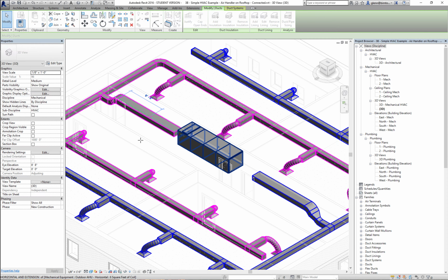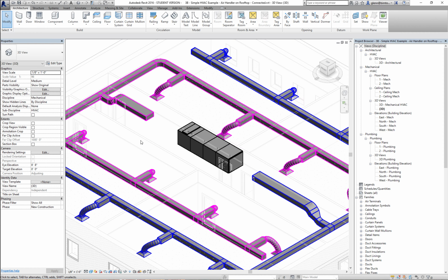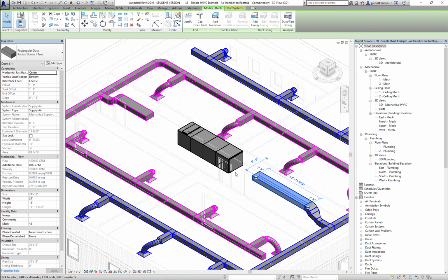And I'm trying to connect these things. Space is definitely one of those things you have to play with. If you're going to have troubles anywhere, the problem you're typically going to have is, do I have enough room to make all the necessary elbows to get this thing aligned right, or taps to get it aligned right, and the reduction to change between the different sizes. So having a little extra space is definitely a good thing for you. But as you think about this, let's talk about what it does do for you.